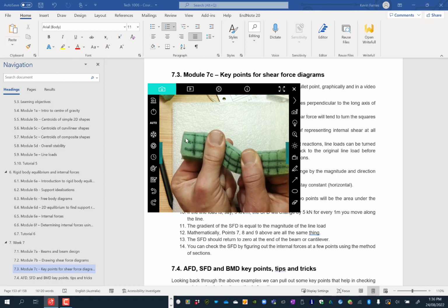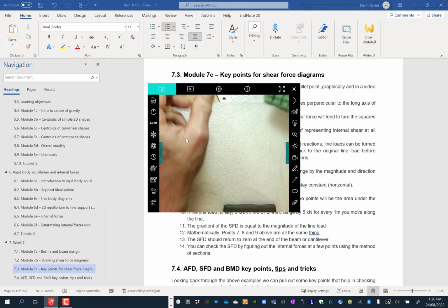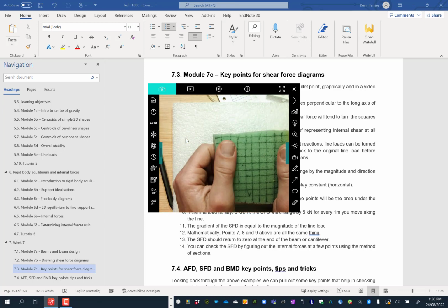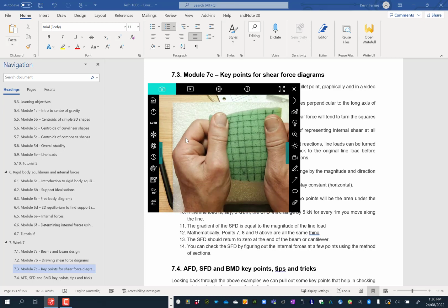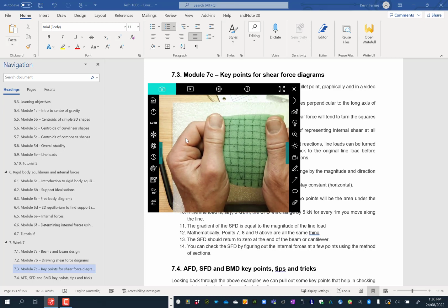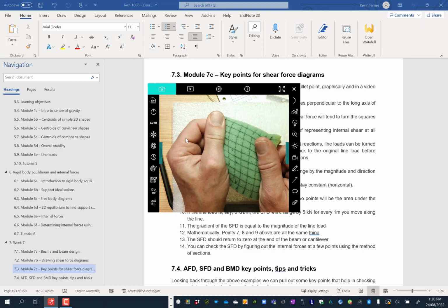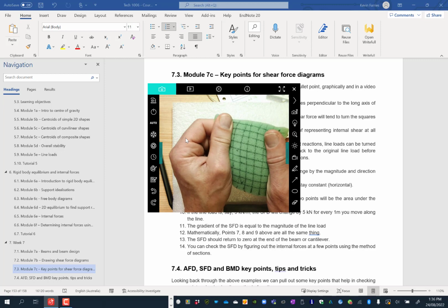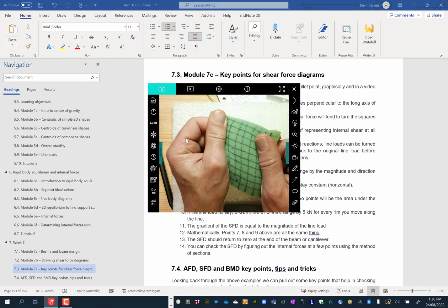So that's a shear. It's a little bit hard to show with a thin element, but with a fat, wide element, it's a little bit easier. It won't be perfect because my fingers aren't exactly straight. You can see how those squares are going a little bit into parallelograms or diamonds. So that's a shear force.